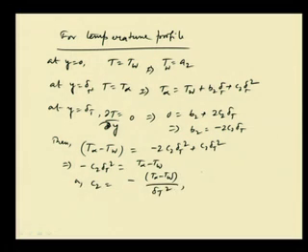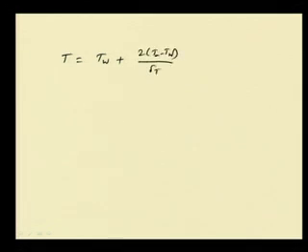And then if we know C 2, then we have B 2 is equal to 2 into T infinity minus T w by delta t. And if we put these expressions, then T is equal to T w for A 2, plus B 2 which is 2 into T infinity minus T w by delta t, plus C 2 which is minus of T infinity minus T w by delta t square, and here it is y, that is y square.